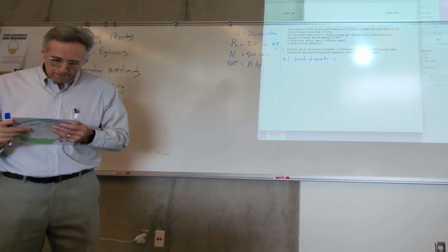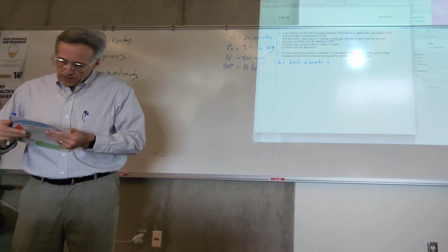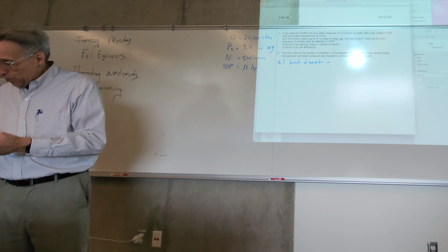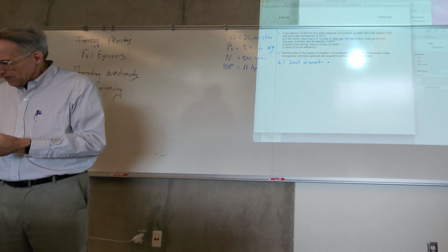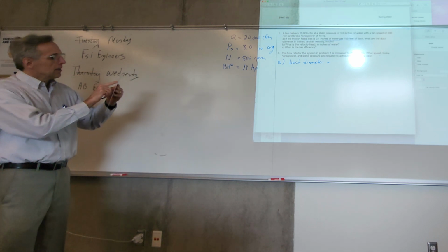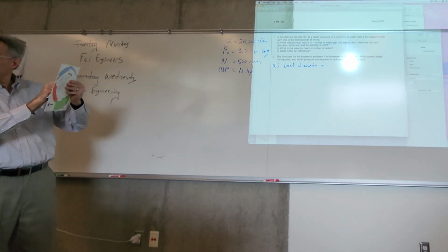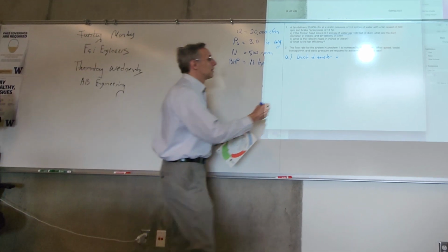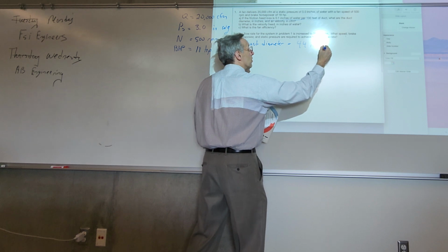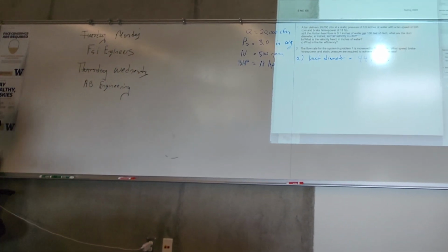area, and we line up 20,000. Oh, I'm on the SI side. So 20,000 CFM is on the outer rim, and we line that up with 0.1. And then we look at the round duct, and it looks like 44, 43 and a half, 44. That's a really big duct.